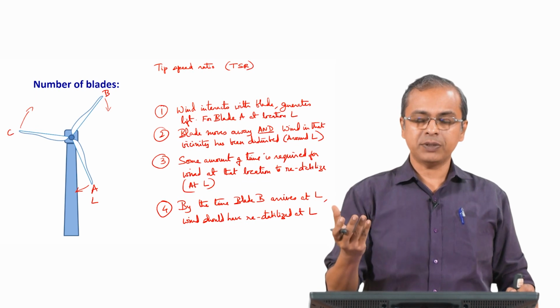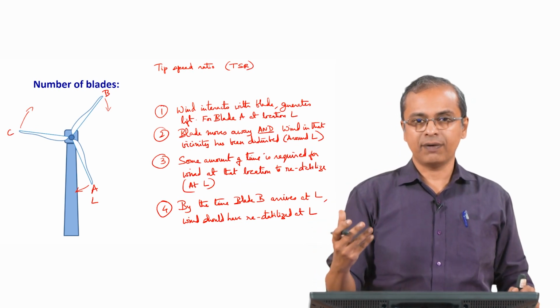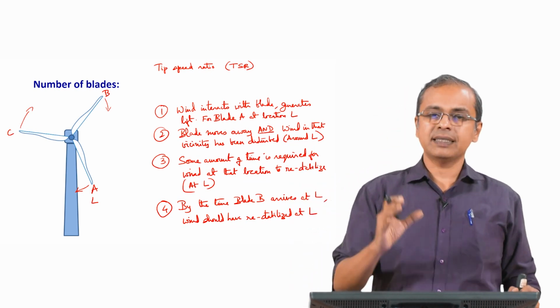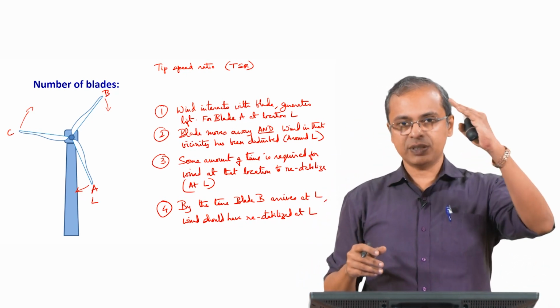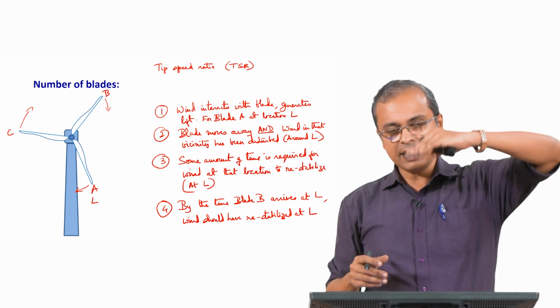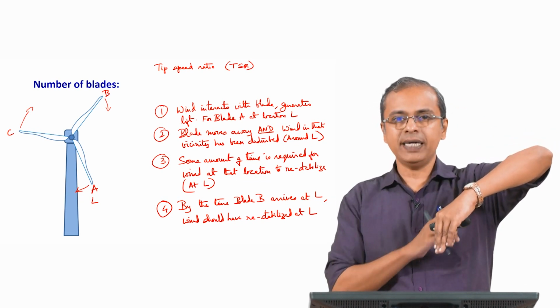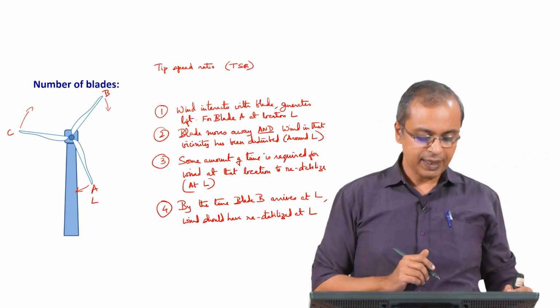The wind has much more energy. You are capturing disturbed energy, only some part of that energy you will capture from the wind. You are not capturing all the energy that is there in the free flowing wind. So, the better design is such that you set it up with a tip speed ratio such that by the time that blade comes to that location vacated by the previous blade, the wind has restabilized. Okay. So, that is how we do this calculation.